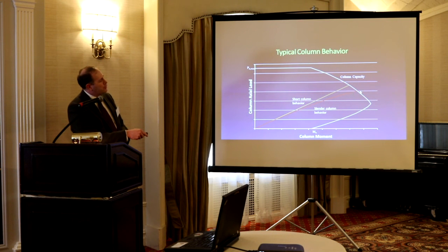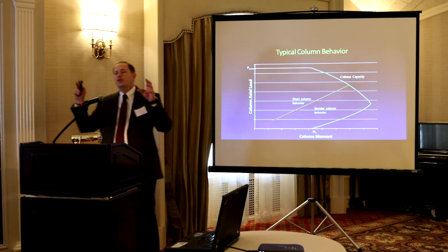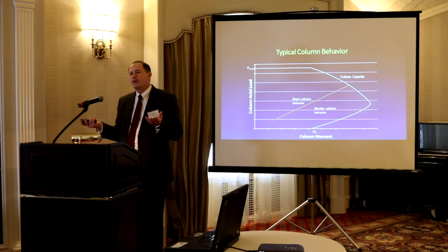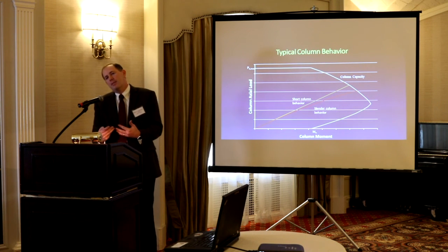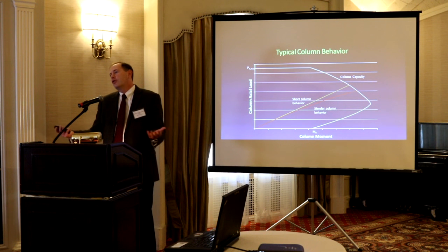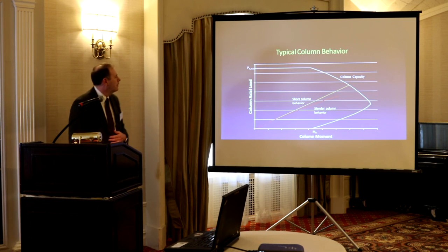And what that results in is, ultimately, when I hit the curve, I'm going to hit it lower, and I have a reduced capacity because of the slenderness. The capacity of the concrete is still the same. It's a matter of, I actually have increased moment I have to resist.